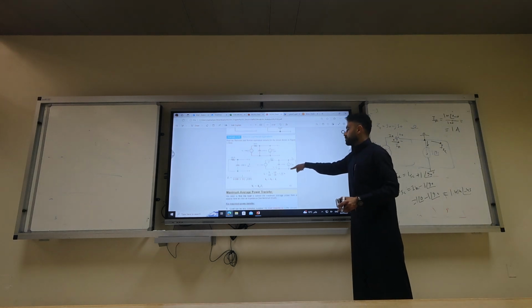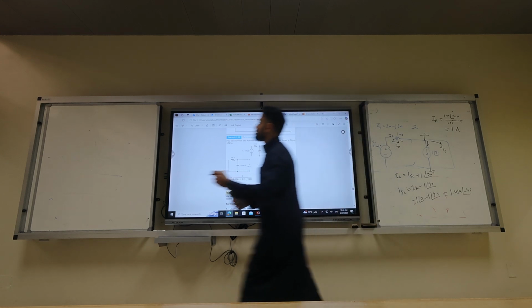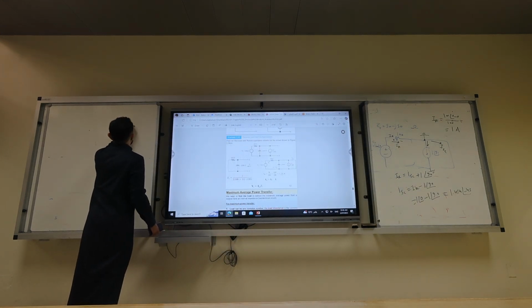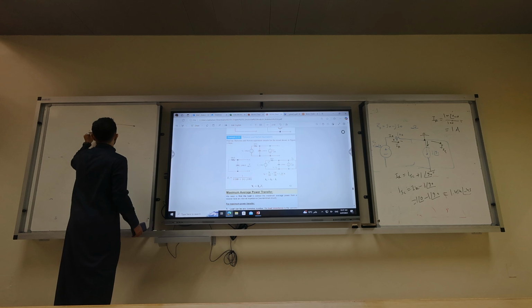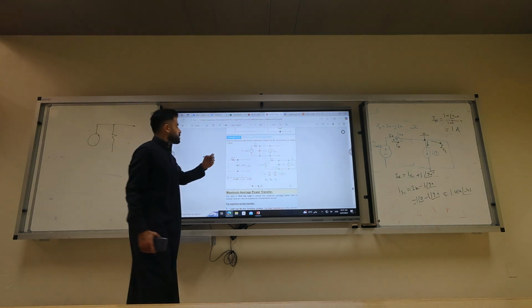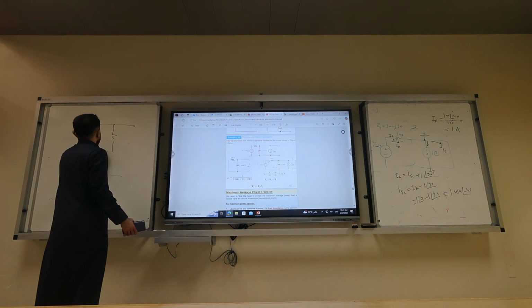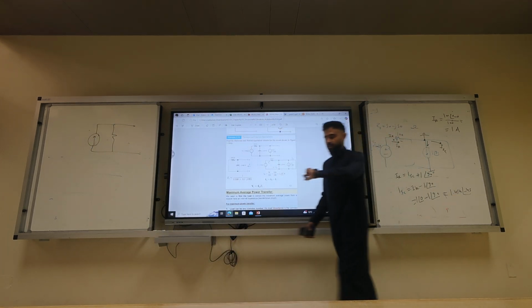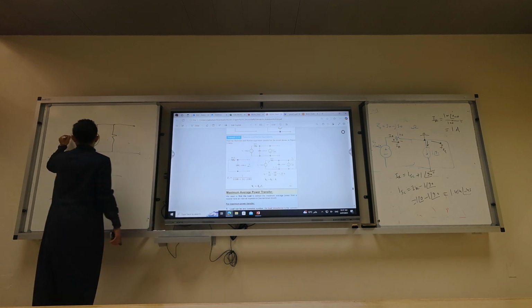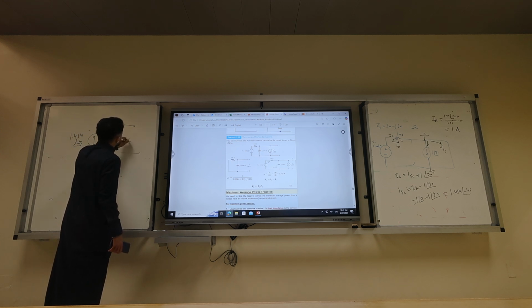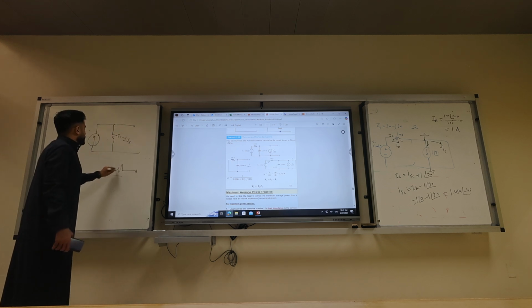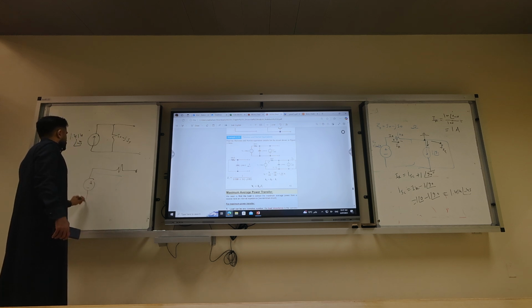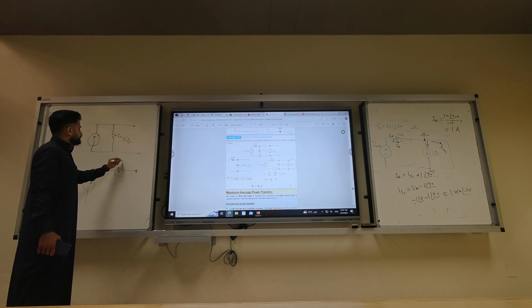So that's the I Norton. So I can write the equivalent Norton model to be R Thévenin. Okay, so I put a current source here. What's the value of that current source? 1.414 angle minus 45. What's R Thévenin? 50 minus J50. Can I find V Thévenin? Put R Thévenin the same.